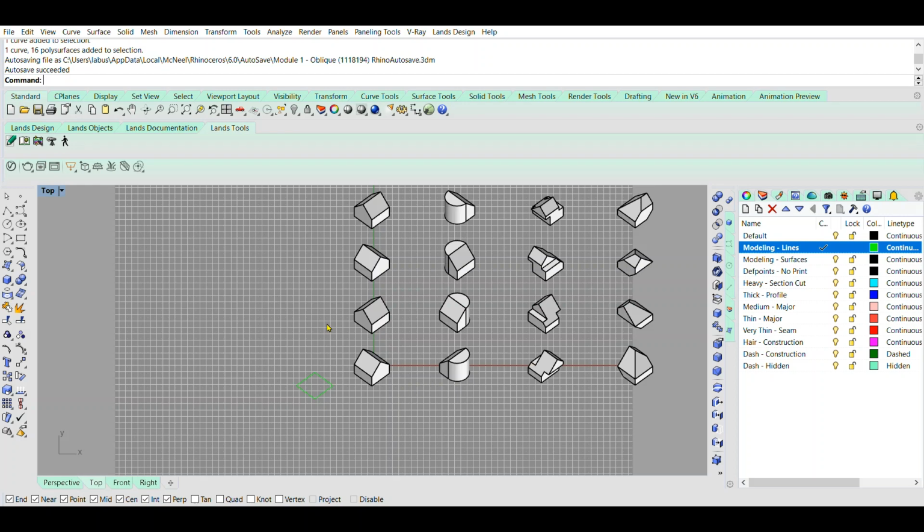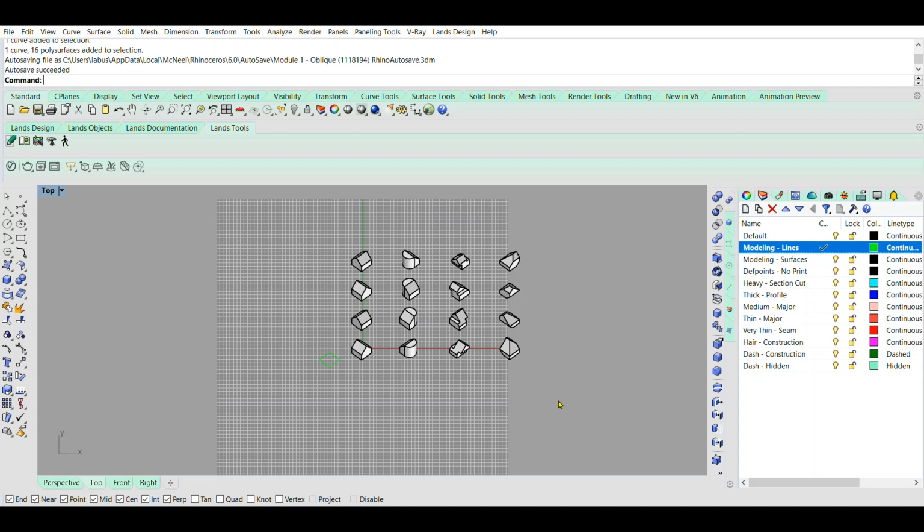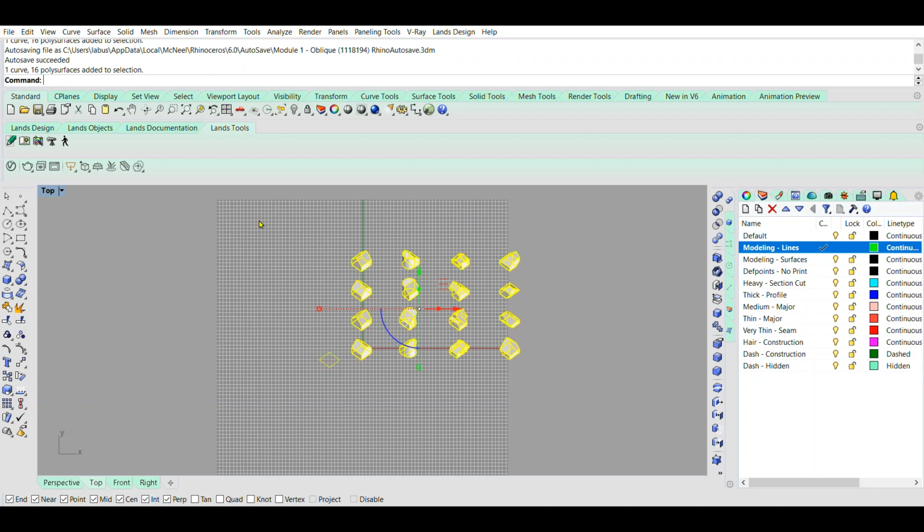So we have this set up. So we're going to select all of this, and Make 2D is a command where it'll take all of your geometry and make an outline of it. And so I hit that command, and for my software, like I've been saying, the dialog boxes haven't been showing up, but it says 2D drawing options. And then my options I'm going to select, it says view. I'm going to keep it with top projection.